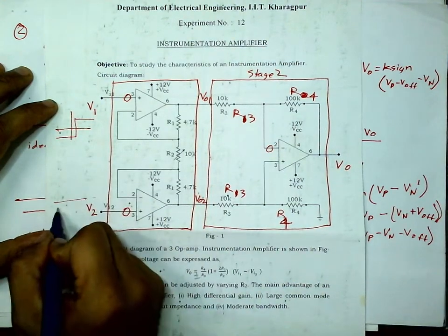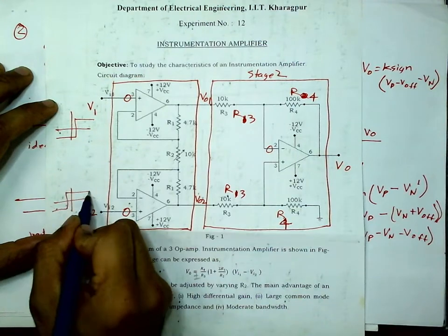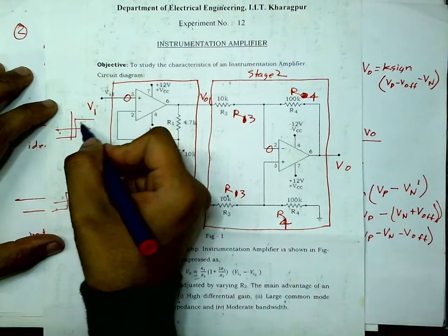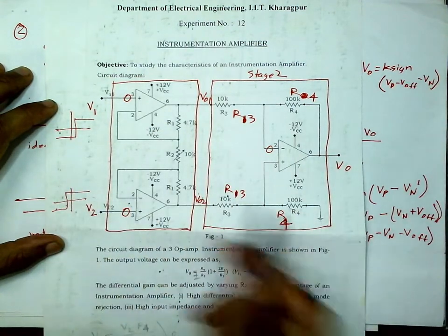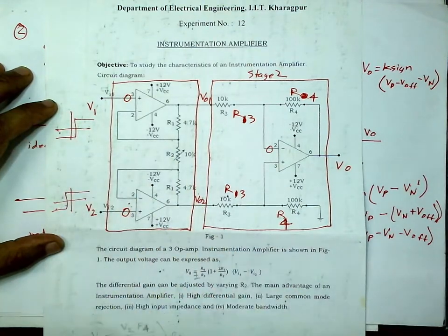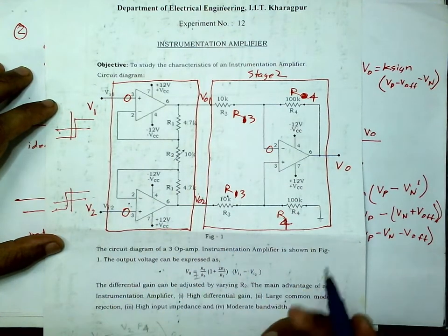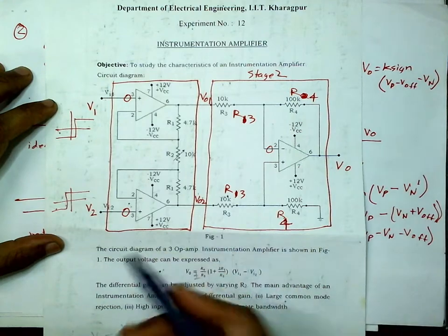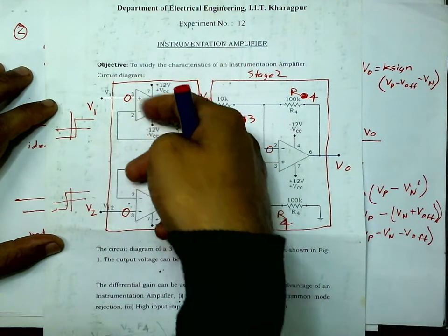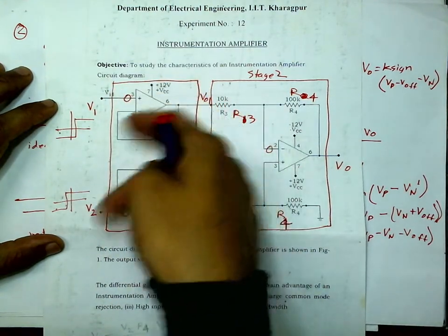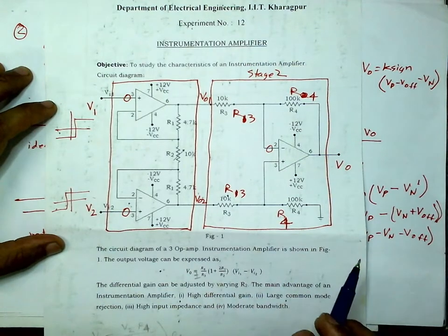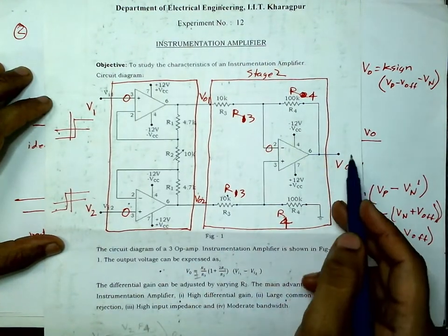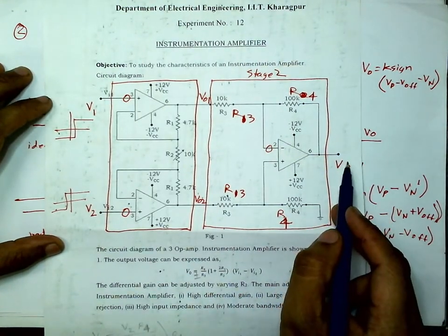Maybe this one looks like this. And this offset voltage can either be plus or minus, positive or negative. That varies. We cannot ascertain it a priori. Even if you take two op amps purchased from the same place, they can have different offset voltages. This can cause some common mode gain.